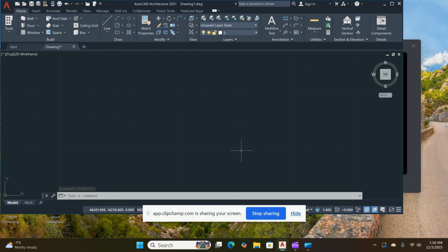We will now proceed to input the straight boundary segments from the survey. AutoCAD uses relative polar coordinates for this task, entered in the format at distance less than bearing, with the bearing expressed as, for example, north 29 degrees 53 minutes 45 seconds east.